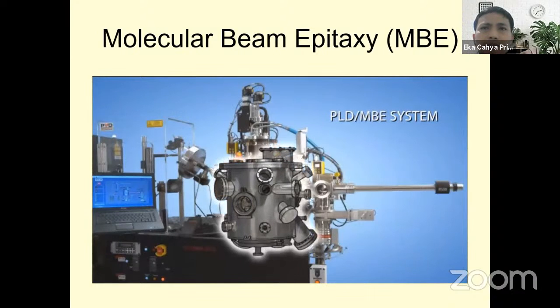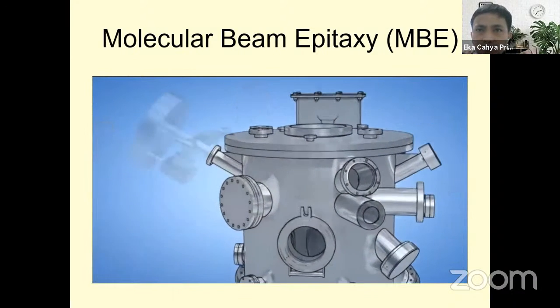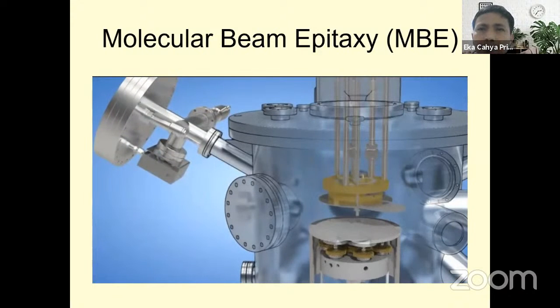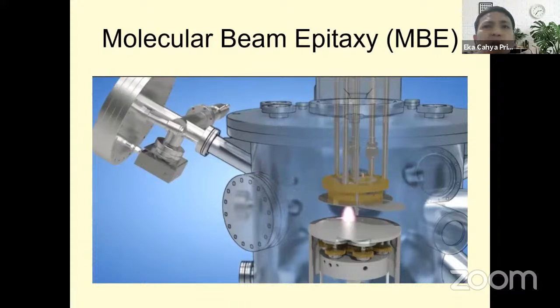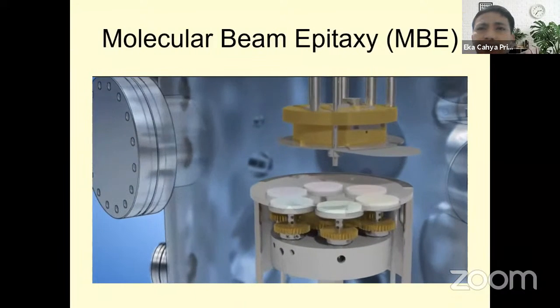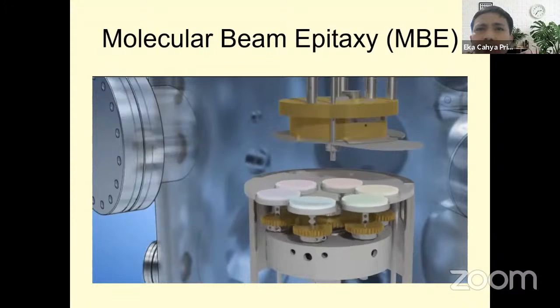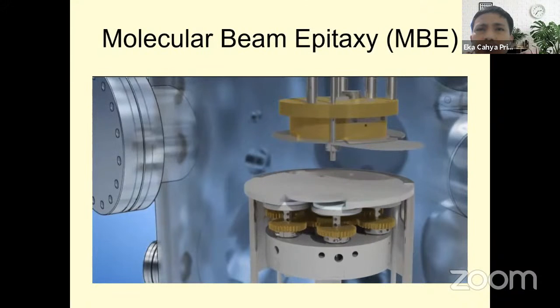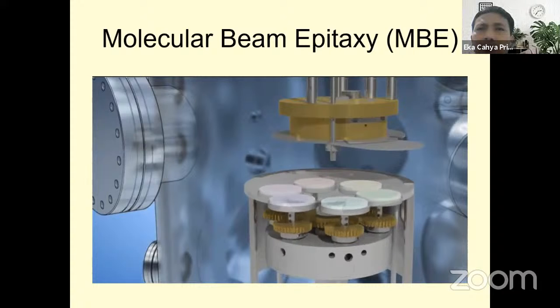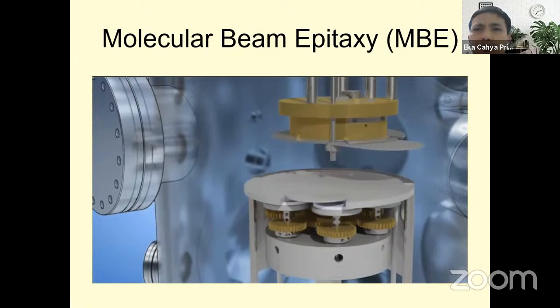Inside the vacuum chamber, standard programmable laser beam rastering provides more uniform target utilization and better film thickness uniformity on the substrate. This simulation shows the growth of a multi-layer film stack of 3 different materials using computer-controlled target indexing and laser firing. Any number of layers, up to 6 materials, can be grown. All PLD MBE systems come standard with 6 2-inch targets and can easily handle smaller targets. The multi-layer stack process can be repeated multiple times via software, and layers from other types of sources can be easily incorporated into the recipe process, as you will see.